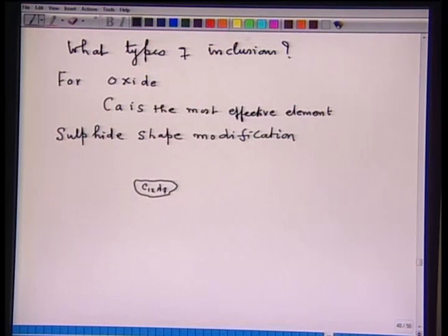Now, this 12CaO·7Al2O3 inclusion has a very high sulfur capacity. That means it can absorb sulfur, and on top of this inclusion one can have the so-called CaS, MnS on the surface of the 12CaO·7Al2O3 inclusion, and if we roll it, on rolling it does not form a stringer type of inclusion.